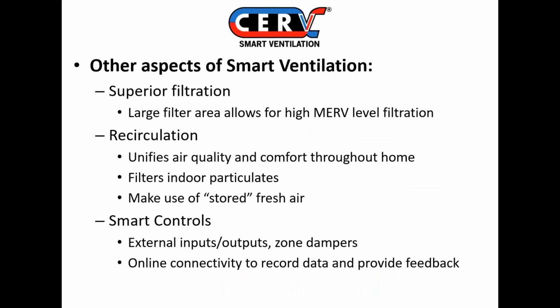Some other aspects of the CERV system are the superior filtration. We have large filter area, which reduces the pressure loss across the filters. So that allows the system to utilize high MERV level filtration. We'll talk about that a bit later, but the standard MERV rating for the CERV is 13.